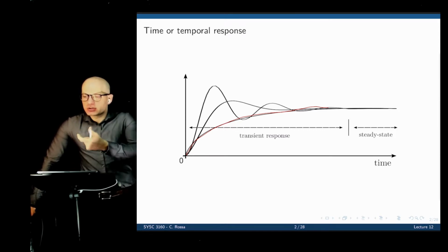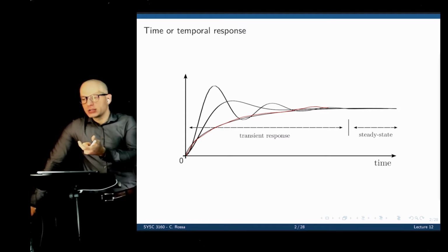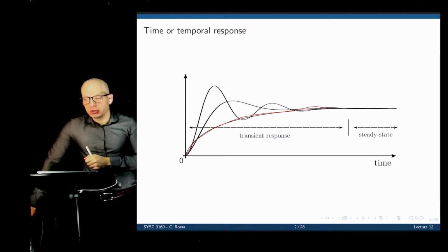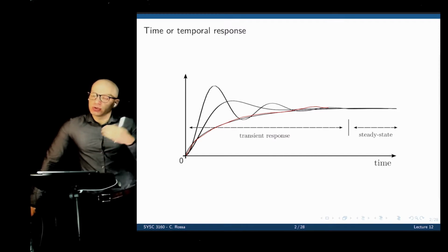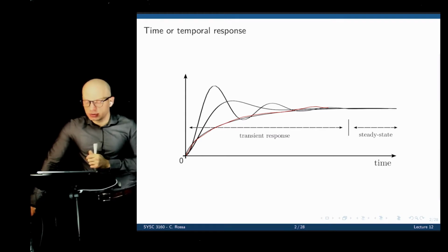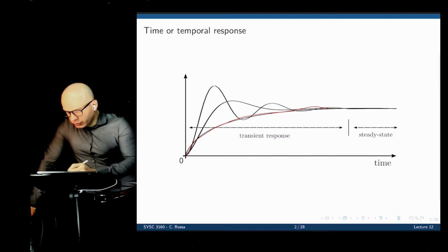The time constant is a real number. The poles of that transfer function are always real numbers. Therefore, when you take the inverse, we always have exponential curves. There are no imaginary components in the poles of first order transfer functions, which is the same way to say what we just said.